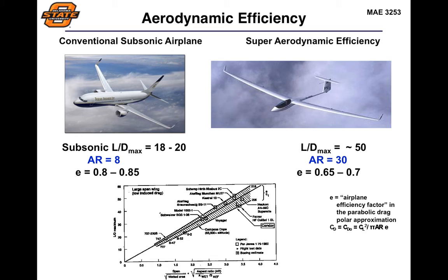And so you can start to derive this then with your aircraft design, thinking about this from the limitations of your operational requirements. Obviously, you'd like to have as high a lift-to-drag ratio as possible, but for a commercial air transport, there's going to be a practical limit. You can exceed that on other types of aircraft design, such as a glider, which does not have those same type of operating constraints. It's a little bit smaller, it's not going to have the same type of wingspan constraints that you would have with the commercial airliner. So it's very difficult to make an air transport aircraft look like a glider and get these really high lift-to-drag ratios.